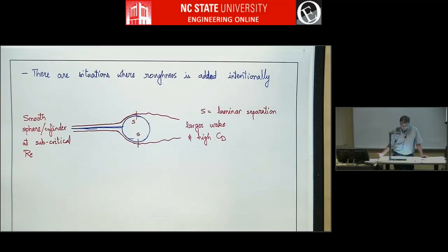But if you want a supercritical Reynolds number, you either have to increase velocity, and sometimes you don't have a choice, or you have to increase diameter, or increase density, or do something like that. Sometimes you don't have a choice, right? If you're talking about golf balls, usually the ball diameter is fixed and the velocity is fixed, so you don't have control over Reynolds number.